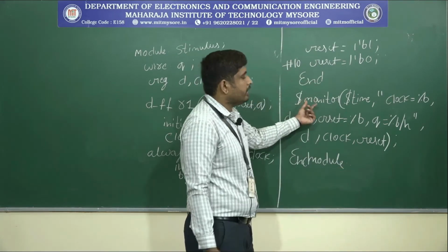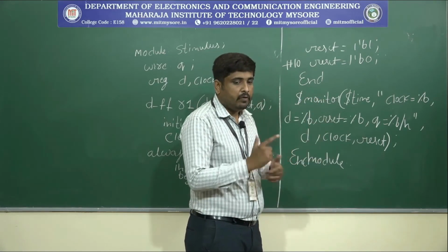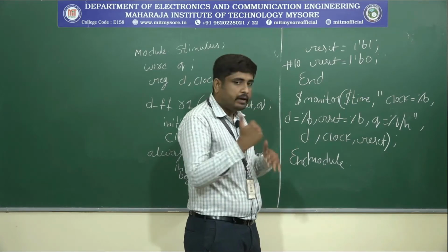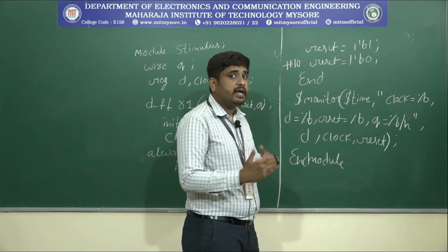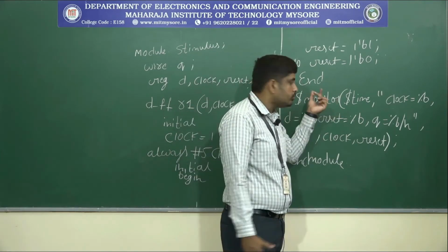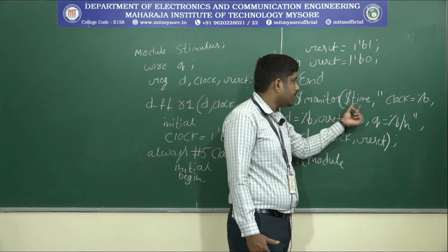We are using monitor because it monitors the current simulation time. When the simulation time changes, at that time it monitors the current simulation time, as well as displays the results. So that's why instead of display we always choose monitor. So $monitor indicates calculation of the current time.